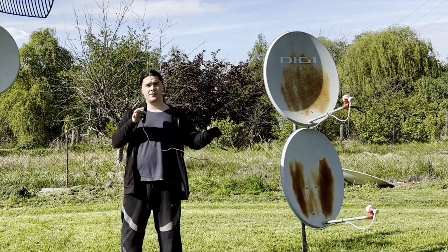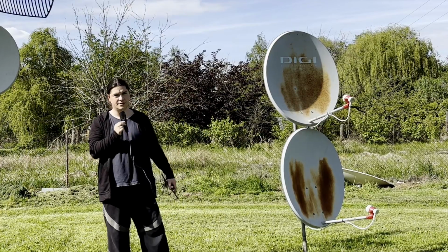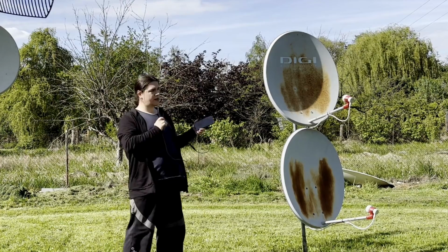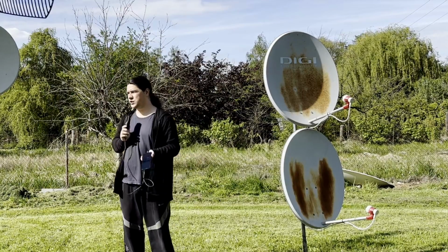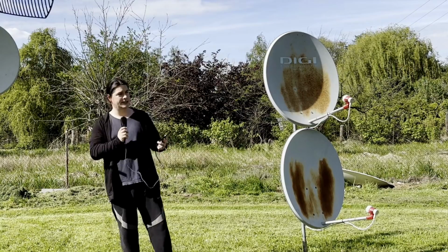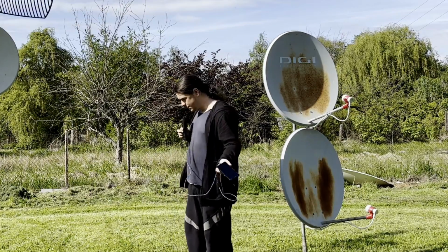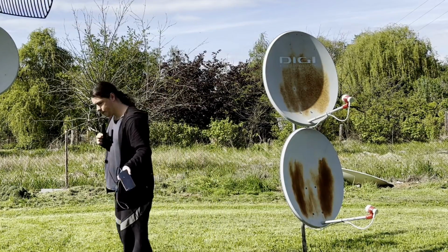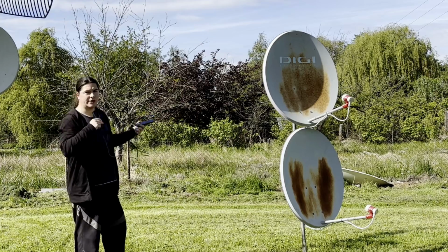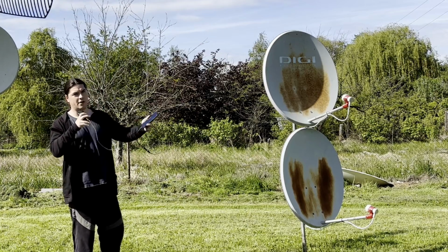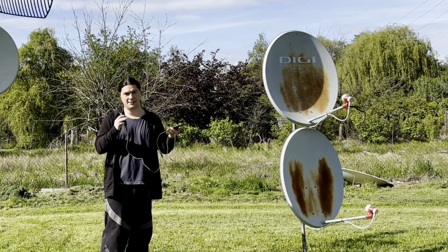Even though the frequency is 10.5 gigahertz, the LNB is actually converting it down to 700-something megahertz. I don't know, I can do math. So any general SDR is going to work. There is no special consideration, I don't think, for the SDR, especially because of the massive conversion gain of the LNB. So when all of this is connected up, you are ready to power up your setup and find the satellite. You can use satellite finder apps to give you a rough idea of where Es'Hail-2 is, because that's how it's probably going to be named in those, since those are meant for TV reception.